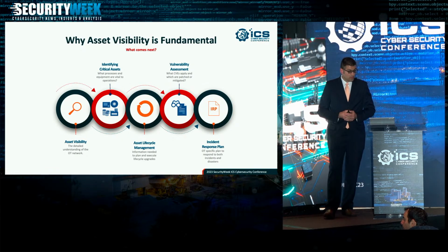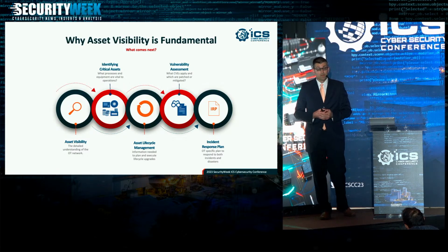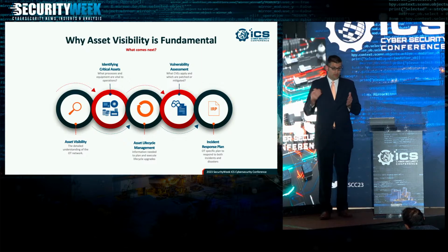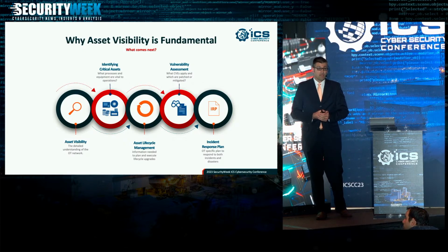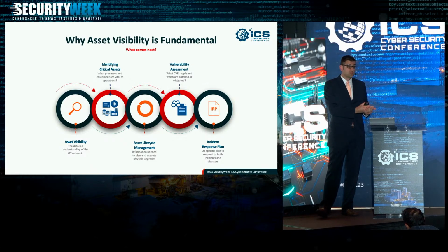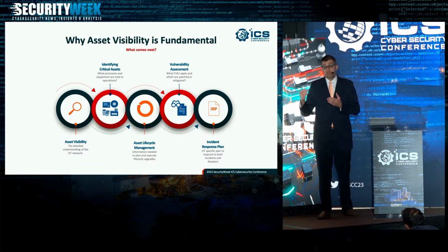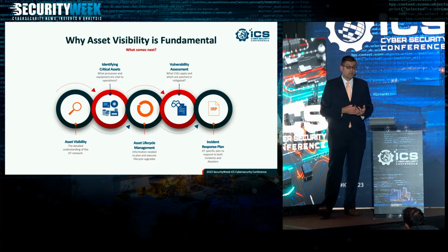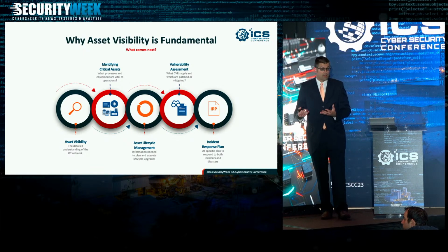A nice example is we knew our core switches in our OT environment were coming up for end of support. We needed to get them replaced. We knew we had a few months left before that. We talked with operations and they said, hey, we've actually got a plant shutdown coming up where we're going to be offline for 2 days. All right, well, let's time it. So we had these core switches replaced during that same period, which makes it easier on operations and easier on us doing the switch replacement. It minimizes the impact that your asset lifecycle upgrades will have.